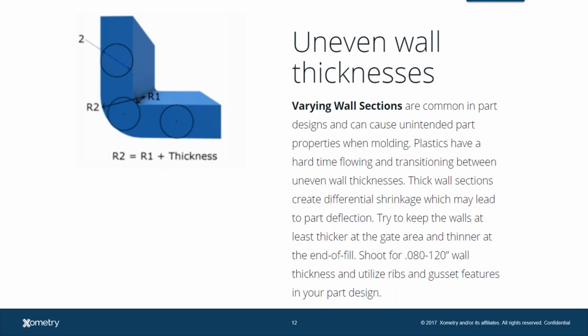One of the things that we see with injection molded parts that have thicker surfaces is something called sink, which almost looks like a thumbprint indentation into your part. And that's literally because there's more stuff there. In that center of mass, it's still hot, and it's shrinking down. It's basically pulling everything else around it, and it becomes a visible, noticeable entity on your part from the outcome.